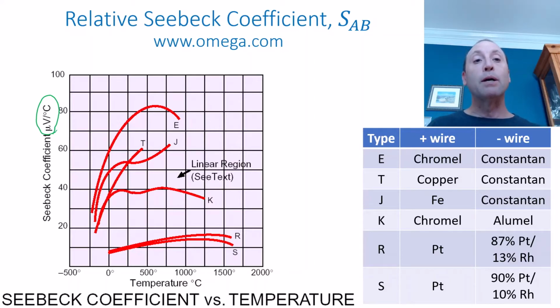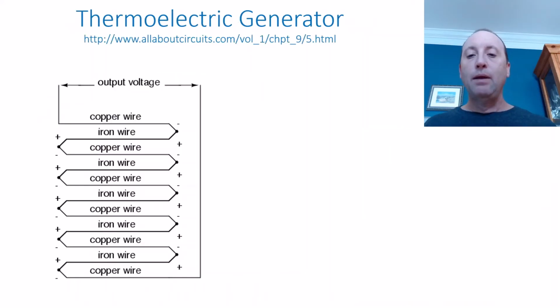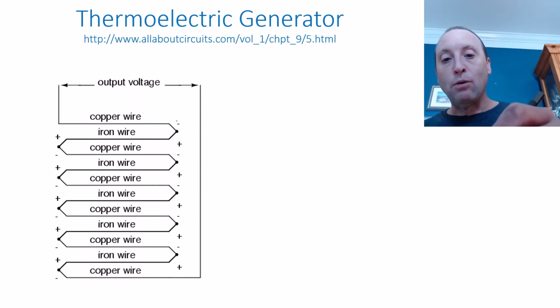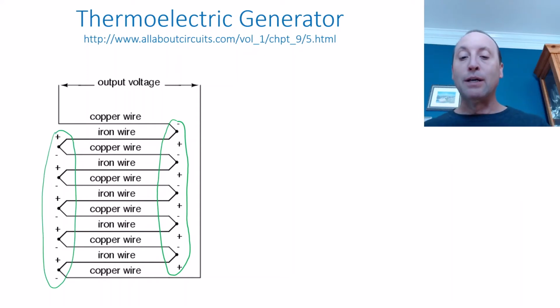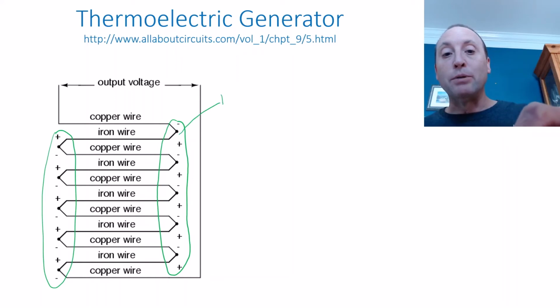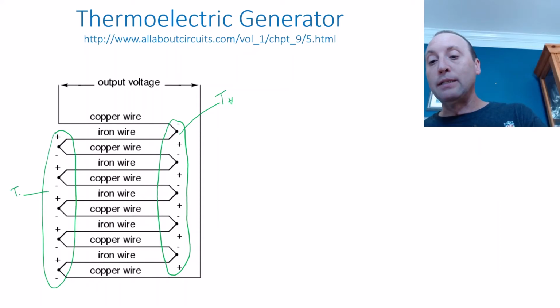What I really wanted to talk about was a solid-state device that can act as a heat engine. Now we can take a number of thermocouples and connect them in series. Here are shown some thermocouples between copper and iron, and there are 1, 2, 3, 4, 5 couples here on the right side, and another 5 couples on the left side. If these 5 couples on the right side were at some high temperature, T high, and the couples on the left-hand side were at T low,